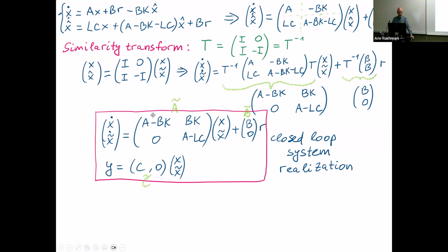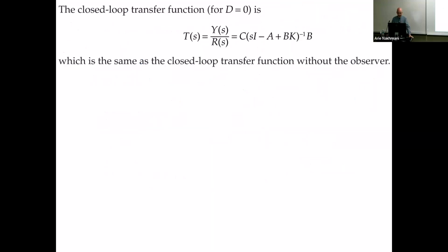Pay attention to the first equation, how the state works. You don't have anything with L here at all, all right? It's not connected to L in any way, right? It's still that matrix A minus BK, and you do not have anything with L at all. So L disappeared from the equation, which means that controller design will not really depend on what L you designed and what you did with your L state. You can design it completely independently.